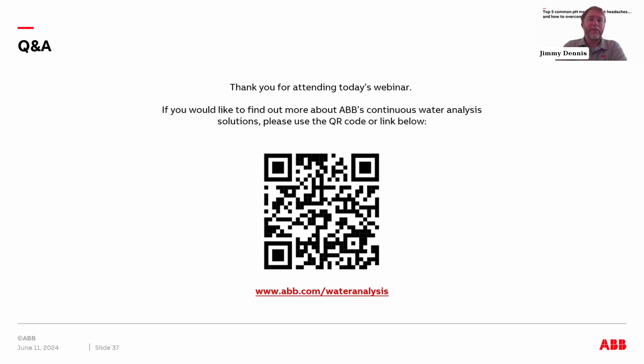So what I typically recommend is to do a buffer calibration monthly using the buffers that Nick talked about earlier. Additionally, it might be good to do a weekly grab sample check, but I wouldn't ever make any changes with the grab sample unless it's 0.5 or greater. And if you're constantly having to make changes, then you need to look at some of the things Nick talked about with cleanings and stuff like that.